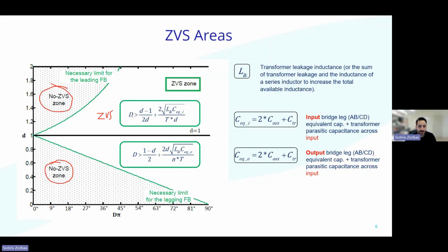Now, what is this? This is the D that we said that we want to phase. Basically, as D comes close to 0.5 actually, dP is a better number. Like, let's play with degrees. If dP is 90, we have full power. That's not a good point to operate, though, because of reactive currents.